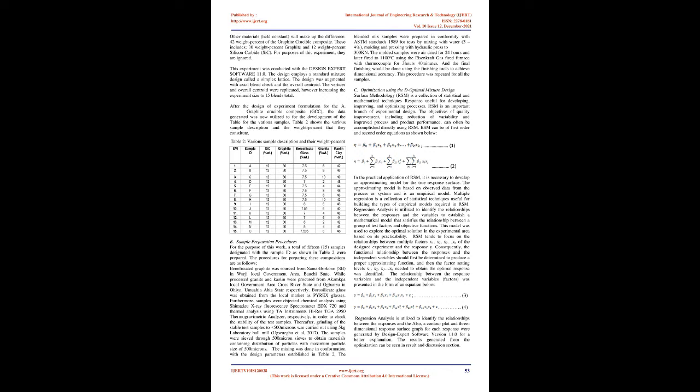7. Studied influence of thermal damage on physical properties of a granite rock: porosity, permeability, and ultrasonic wave evolutions. Parameters for characterization of connected porosity and overall damage in the thermally cracked rocks of granite, in order to access respectively its transport properties and its mechanical strength, are identified and quantified. Samples were heated to a range of peak temperature up to 600 degrees Celsius at ambient pressure. Characterization was made by measurement of porosity, gas permeability, velocity, and attenuation of ultrasonic waves. The results confirm the strong influence of thermal damage on physical properties and show clearly the potential of this technique.